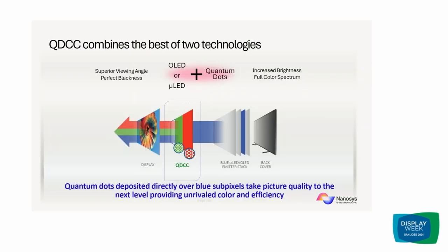So beyond photoluminescent technologies, we're now moving into these photoemissive technologies. The first here is quantum dot color conversion. Previously, if you go back about 5 years ago, people considered quantum dot televisions and OLED televisions as completely separate technologies. But today, it's actually possible that you compare these two pretty seamlessly. And in this context, it's color conversion with quantum dots on blue OLED.